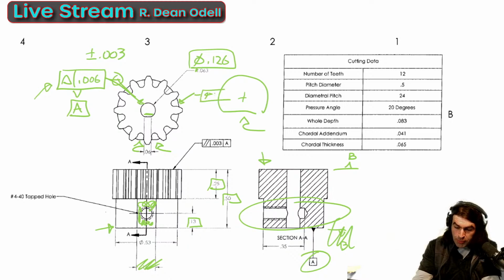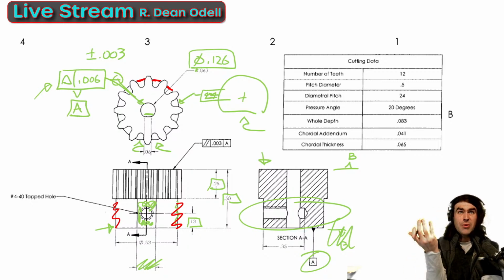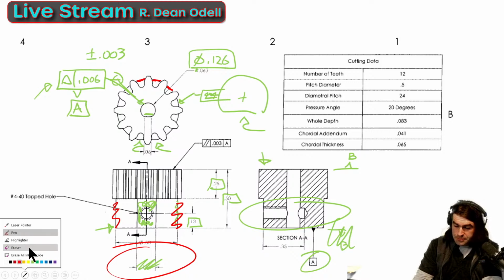And this is a horrible way to do it, right? You typically don't want to apply something to where it's only halfway visible. So what I mean is this cylinder, let me mark it in red. This cylinder is visible over here, but it's really not a great way to dimension stuff. You'd really want another view. This is front, top, and you would want the bottom view of that. Okay.